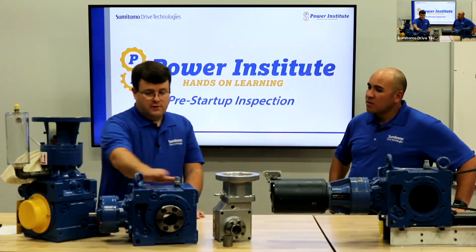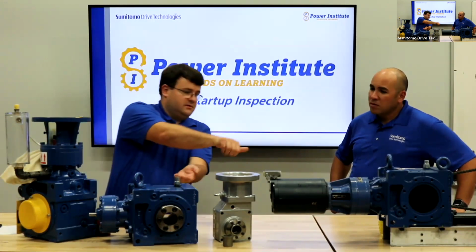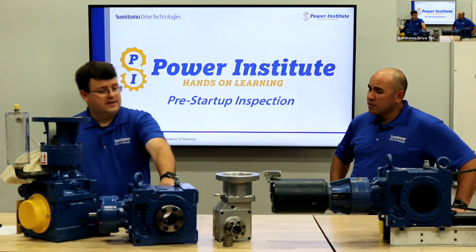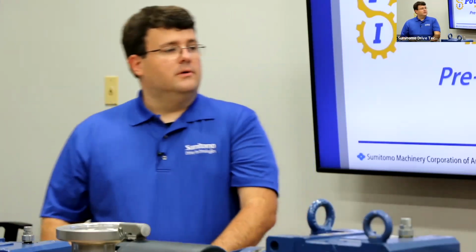Same thing with horizontal and oil. If you're going from Y1 or Y3, as we call it, so horizontal this way versus horizontal this way, you can just flip that with no problem. You just change your breather location and your plug. Gotcha. Otherwise, oil is going to come out of your breather. But grease is the universal one. You can put that any which way. Oil is the more critical one.